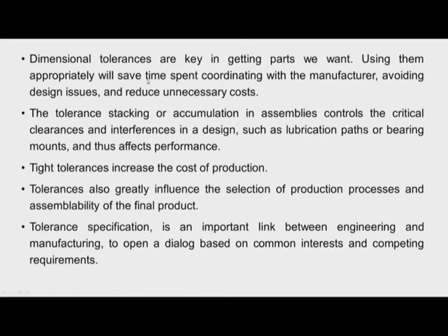So the dimensional tolerances are key in getting parts what we require, and using them appropriately will save time spent coordinating with the manufacturer, avoid design issues and reduce unnecessary costs. And tolerance stacking or accumulation in assemblies controls the critical clearances and interferences in a design, such as lubrication paths or bearing mounts, and thus the performance is affected.